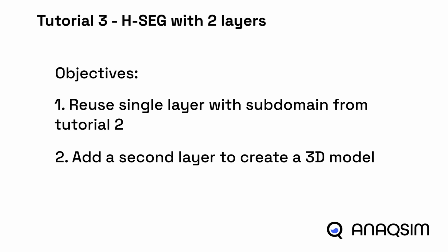Up to this point, we've created 2D models using a single layer. While you can adjust the thickness of that layer to match your aquifer, those models can't capture true 3D flow effects. By adding layers, you'll be able to simulate more complex groundwater systems, like aquifers separated by aquitards or multi-layered flow systems that are common in real-world projects.